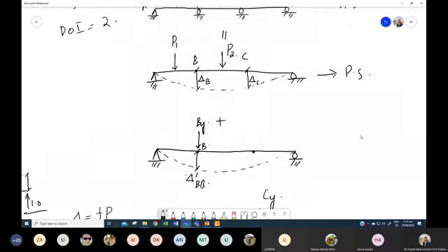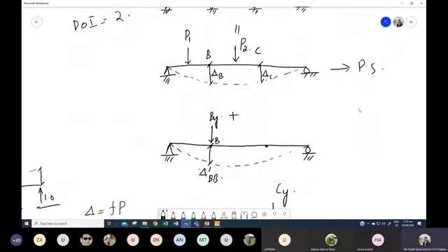Okay. Now there is another thing. When this force By is acting at support B, it will also produce some kind of deflection at this particular support, which is point C. We will call this deflection at point C as delta dash CB. Now this notation means that this is the deflection at point C due to this load at point B.